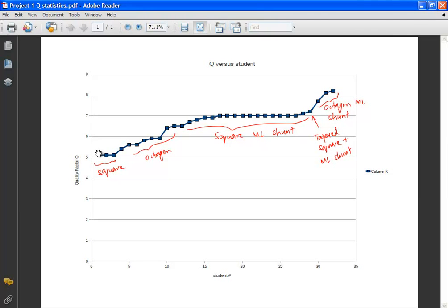Okay, so you will want to try to be somewhere here. You will want to try to maximize. By the way, of course, we have changed the ASITIC technology file after that, so you can imagine all of these things shifting up. Okay, so the performance of your VCO will directly depend on the Q of your inductor. That is the reason why I wanted to show you what other people have done, so that you can use this knowledge.